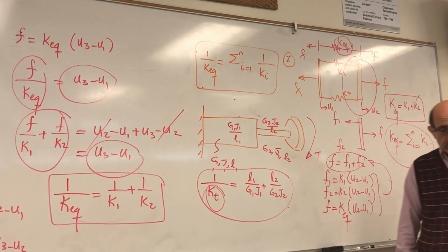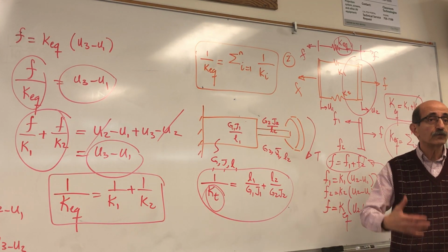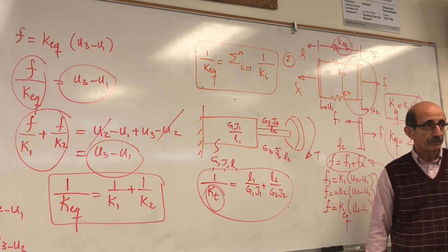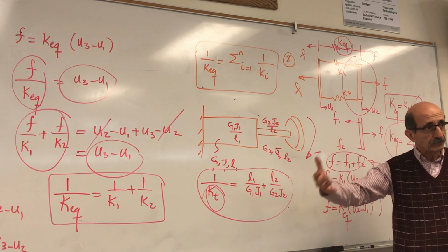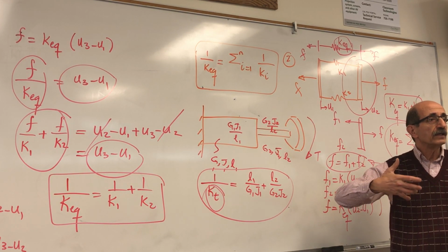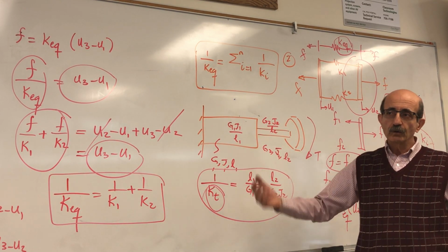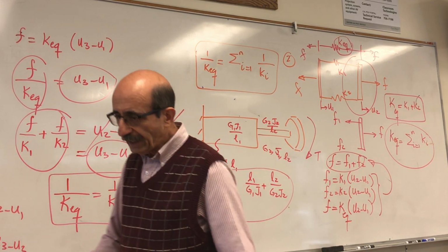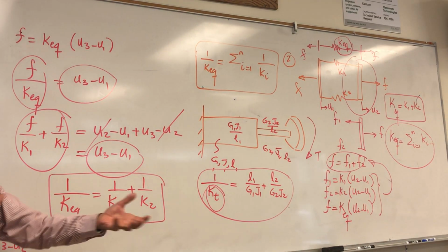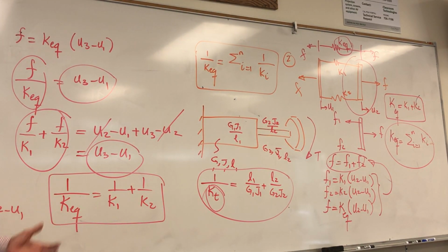For instance, why it is important: if you don't recognize that these stiffnesses are in, say, series, you may say, okay, I have a rotating machinery, and it happens that the support system, these bearings, are in series.